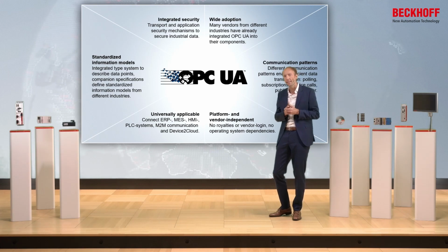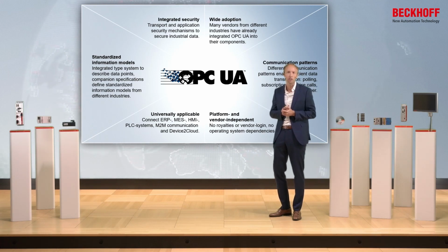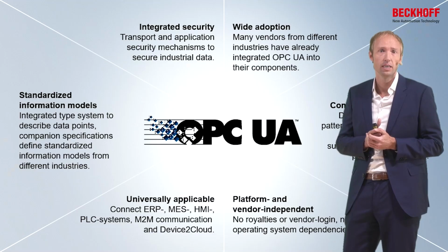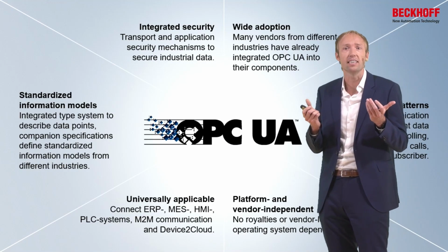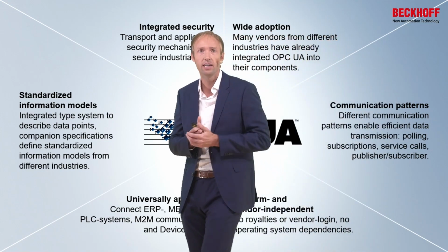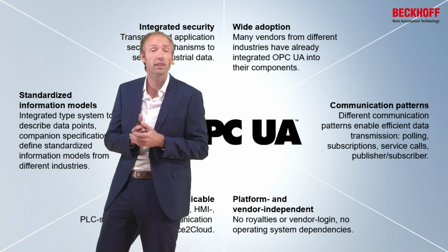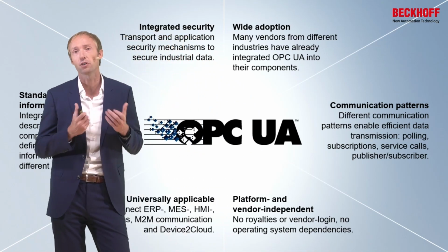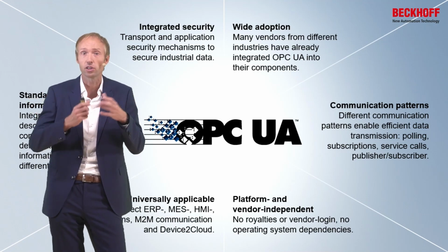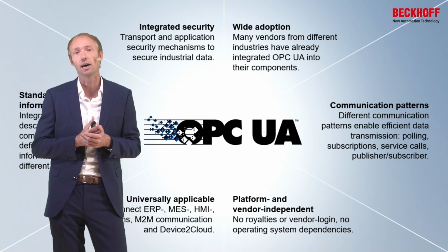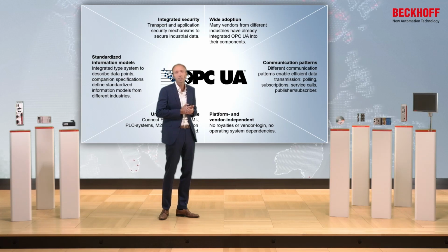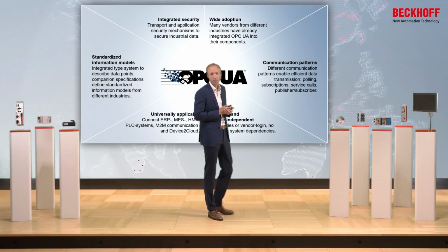Like I said, OPC UA is another important communication technology, which we offer in different products and which we will introduce later on. During the last few years, OPC UA has seen a very high adoption rate across different industries, and it can be seen as the standard that enables industrial interoperability with integrated security mechanisms and possibilities for information modeling across all layers of industrial connectivity, ranging from sensor and PLC devices up to the ERP system and the cloud. But let's have a look first at our common history with OPC UA as a technology and the OPC